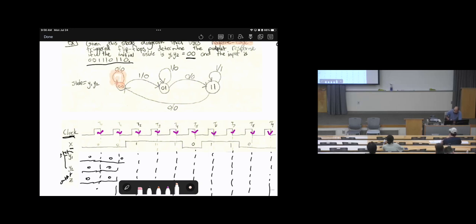We will go back to 0, right? So the state will still be 0. The next update of the states will be at the next trigger edge. While, remember, this is Mealy model. The output is a function of both the input and the states, right?